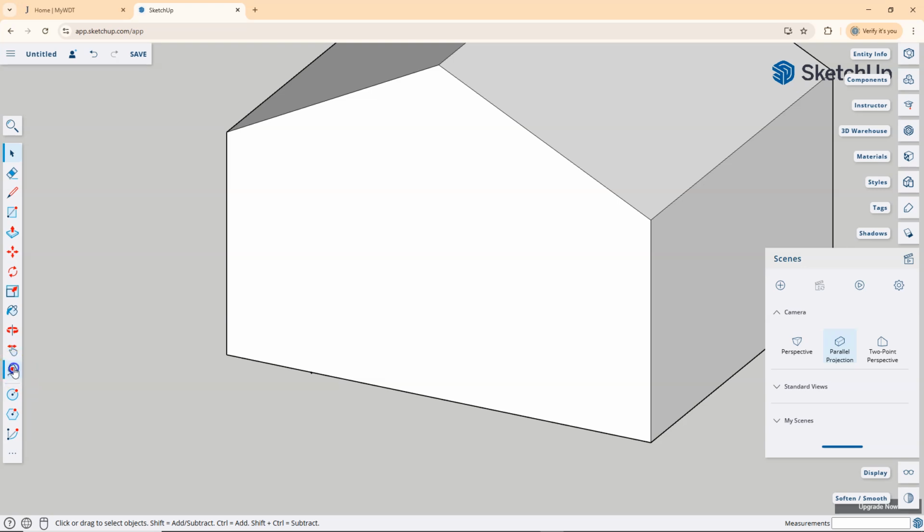As you might have guessed, we can also use the measure tool to see how long things are. So if I just come down here and hover, I don't even have to click my second point. It'll give me a little preview. That's exactly 20 feet. This is exactly 10 feet. We can do it along angled lines as well. So 2 purposes for that measure tool. One of them is to mark a location for the purpose of creating additional things at a specific distance, and then the other one is just to measure things. By the way, if you want to close these boxes that fly out if they get in the way, you can just click on the symbol again. So click it a second time, it just toggles on and off.